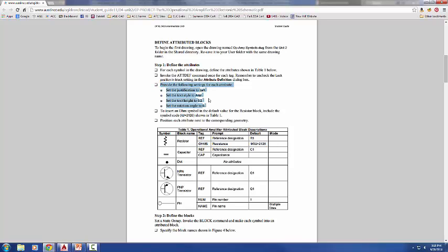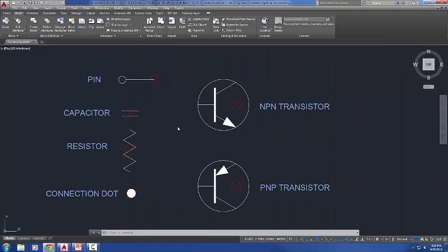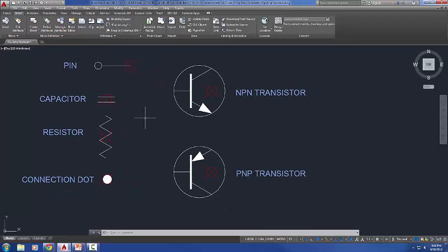And let me show you what happens if I do. So I'm going to come into this viewport, which is supposed to be my first floor. If I select first floor here, looks good. But when I come to this viewport, which is supposed to be my second floor, they both change. For some reason, and it's just a glitch in AutoCAD, when I change the layer states by using this pull-down list, it affects it everywhere. So I'm going to undo, get it back to where it was before, and this time I'm going to show you how you can make it work.